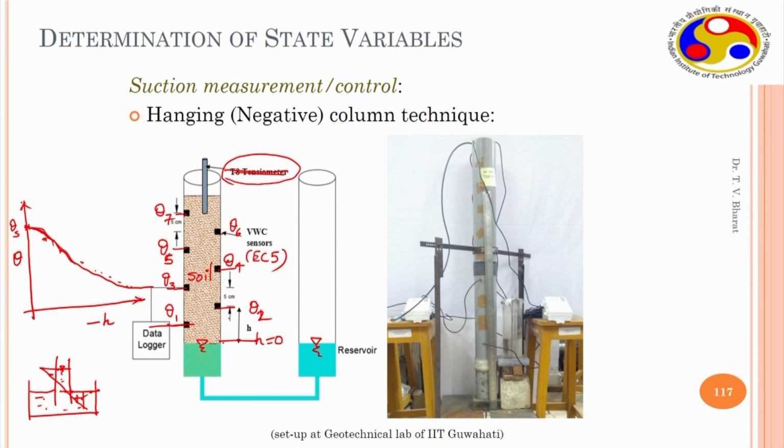Up to that point, that head is called the air entry value or air entry suction head. So, that is somewhere here. Beyond that you have partly saturated. You may have a fully saturated system up to a certain depth, that is HAEV, air entry value head. This is an actual setup that is available at the IIT Guwahati Geotech lab.